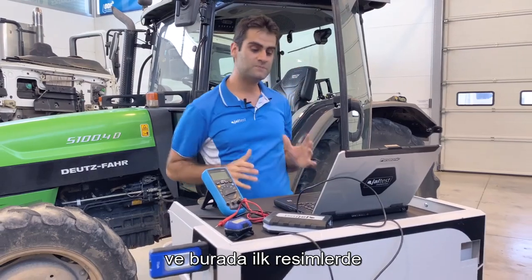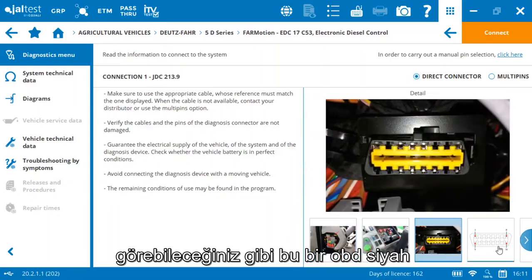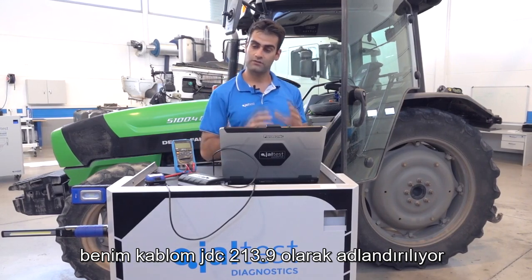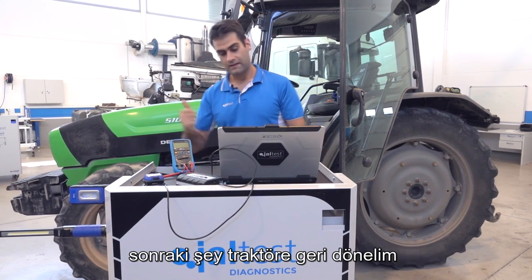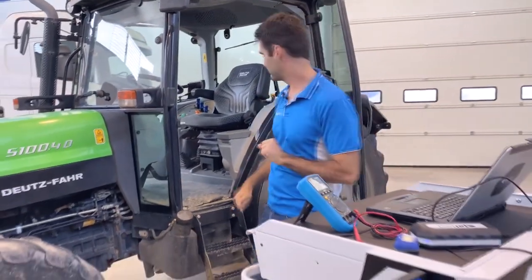And here, in the first pictures, we have a nice overview of where the connector is located. As I can see, it's an OBD socket. And my cable is called JDC 213.9, which is the most generic diagnostic cable for all vehicles: commercial vehicles, construction machinery, and also agricultural vehicles. Next, let's come back to the tractor and see if we can locate this connector and if it's in the same position as Jaltest says.